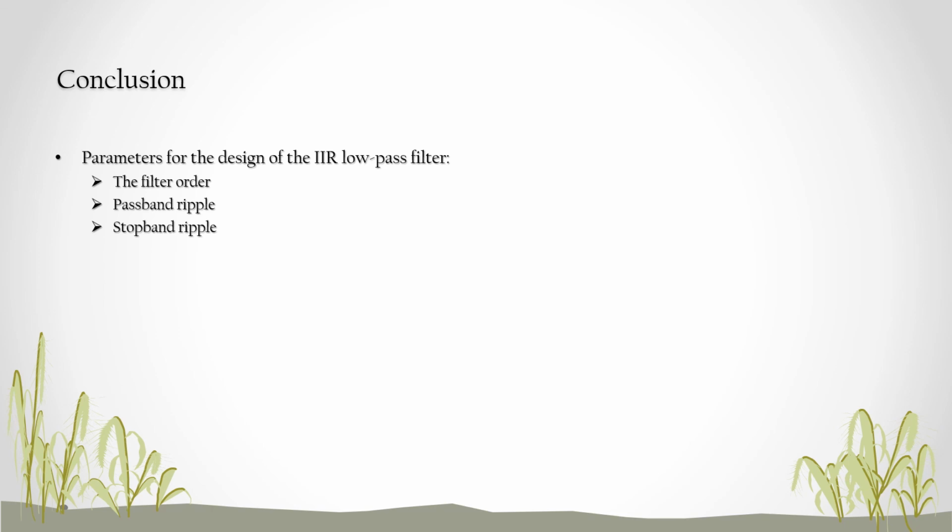The choice for the best approximation depends on what signal characteristics are important. If an application requires low component count, but neither passband ripple nor group delay is important, the Chebyshev type 1 or 2 or elliptic filters prove to be a better choice than the Butterworth one.